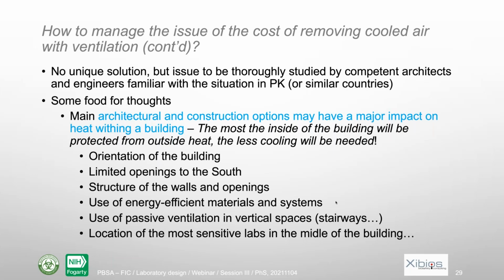Some considerations. The first thing to do, which is very important, is the architecture and also the construction means. These might have a major impact on the heat within a building. The more heat you have inside the building, the more cooling you will need. And if you prevent that heat from accumulating within the building by good construction techniques, for instance, you will need much less cooling. And this is not a job for laboratory people. It's really work for architects and engineers.